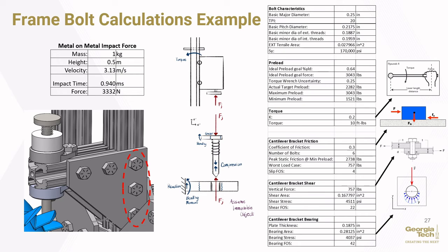Because the firing pin is on aluminum cantilever beams supported by corner brackets, the bolts that will be receiving the most shear force require machine design calculations to ensure they will withstand multiple high-impact forces. Additionally, the force on the cantilever will create a moment, thus the 3 bolts will not endure the same stress concentration, which was reflected by the calculations.